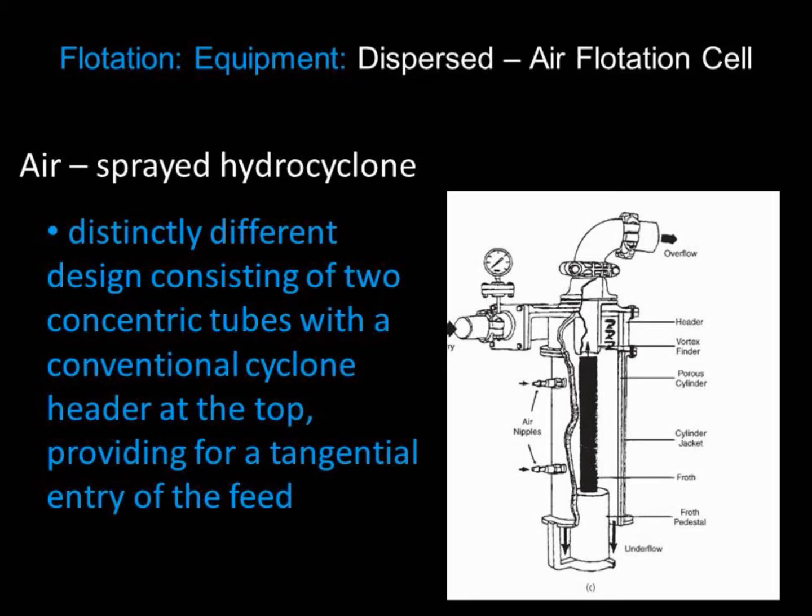The bubble-hydrophobic particle aggregates are transported into the overflow stream as froth, while the non-floating particles are removed with the underflow. Each of these and other design variations to the basic pneumatic flotation column concept is found to offer process improvements to specific applications.